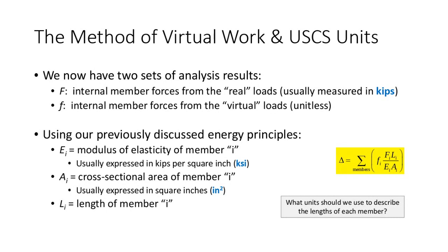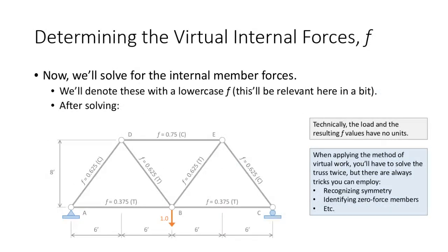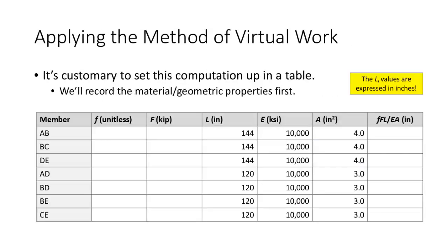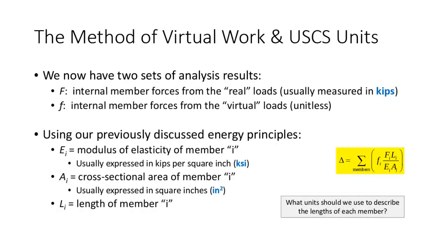Let me ask you a question. What should we express the length of the member in? Because normally when we look at a truss analysis, let's go back to our previous slides. Here's the truss, and the truss is in feet. That's 6 feet long, 8 feet long. So convert all of your member lengths to inches. Okay, that's very important.